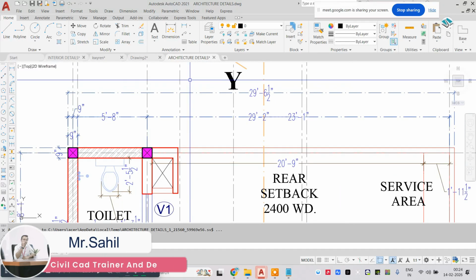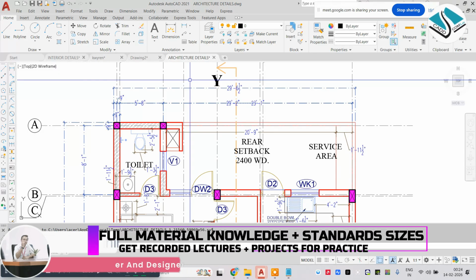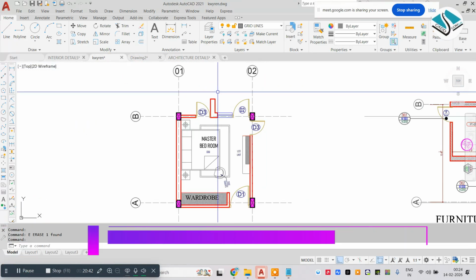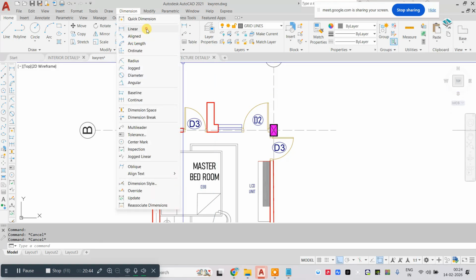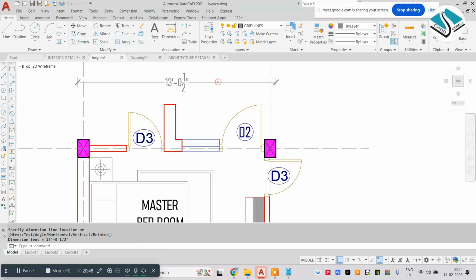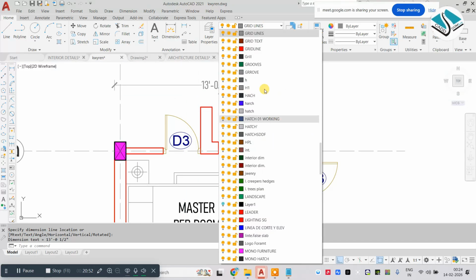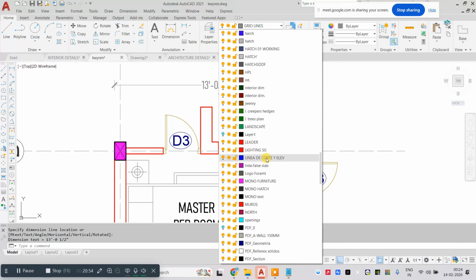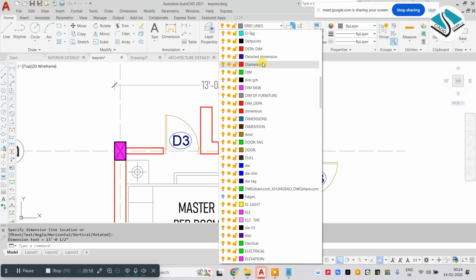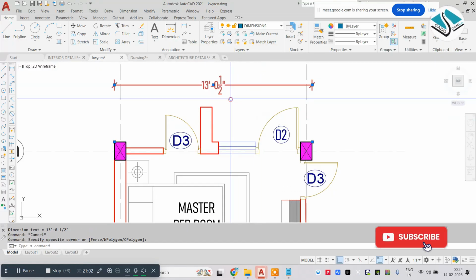Then after that, we mention the dimensioning, outer and inner area. Also, the same process we will use here. There are no changes. So first, we will use the dimensions outer to outer. So use your grids, like we will use the different grid lines. Press D. Where is dimensions? We will use this layer.